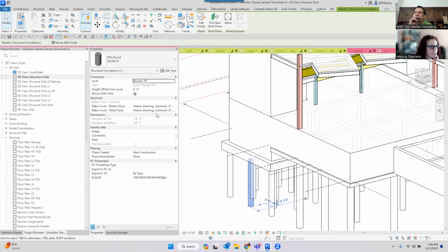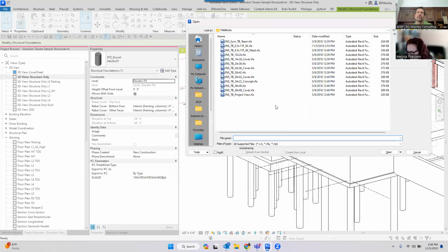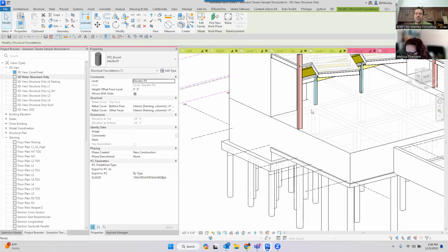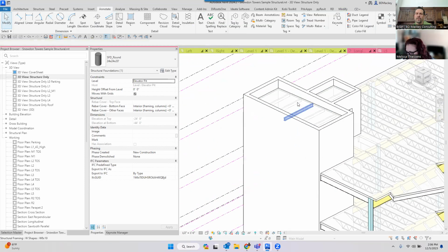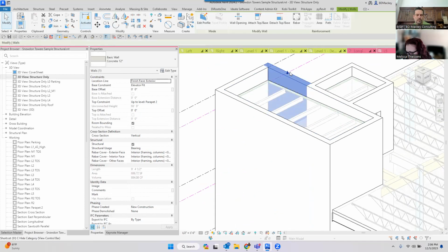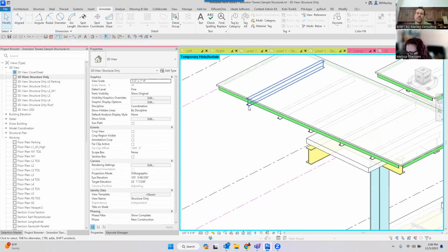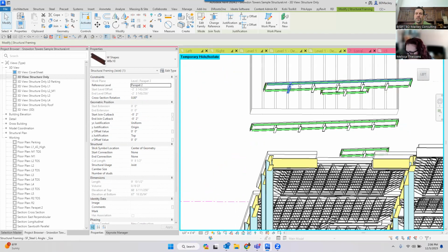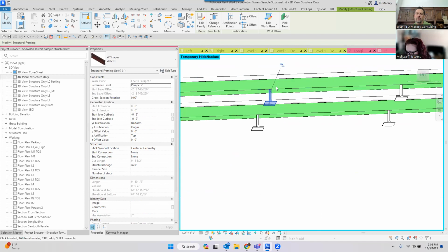Okay, let's see. What do you think is the best way to do slopes and counterslope roof systems for structural? What's the best way to pitch 1,000 joists for the counterslopes, high point and low point? If you're pitching joists, then I would not be modeling them flat. I would be modeling them associated to what I always call, actually, I have it inside of here. So if I needed to change the elevation of all of these here, what I've done inside of this one, my high wall category, is I wanted these to be plumb, not perpendicular to the work plane.